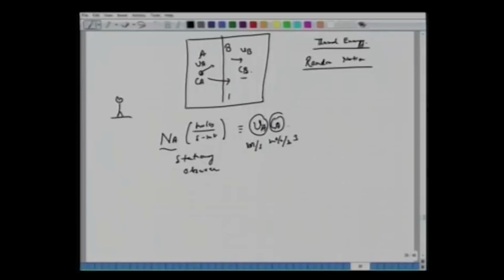So this observer is stationary. He will measure VA CA, but this will contain two quantities here. One, say the mole fraction of this species is XA at this plane. So XA into N. What is N? N is nothing but NA plus NB. So there's one component. When entire A plus B they move along with this, they also carry this XA. Plus, there's another component which is Fick's first law, molecular diffusion. So this diffusion is over and above this.